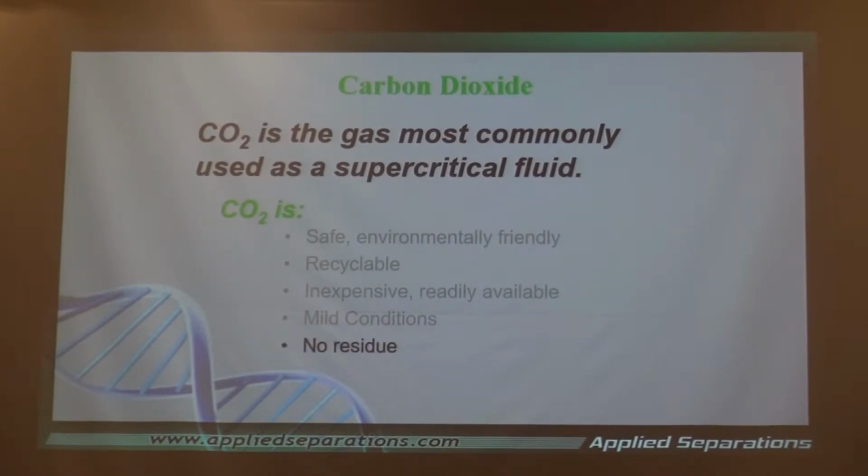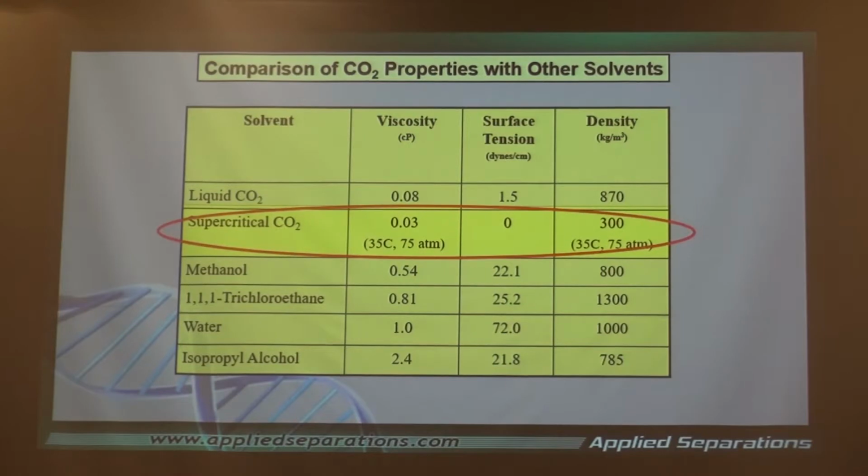As we pointed out with the coffee and the decaffeination, when we come back to ambient, there is no residue. It has zero surface tension. Well, take a look. Surface tension, 0, compared to the other solvents. This allows it to get into the small spaces. You're not held up at all. It gives you the ability to move in and out faster. You can do these extractions because you are not now limited by surface tension.